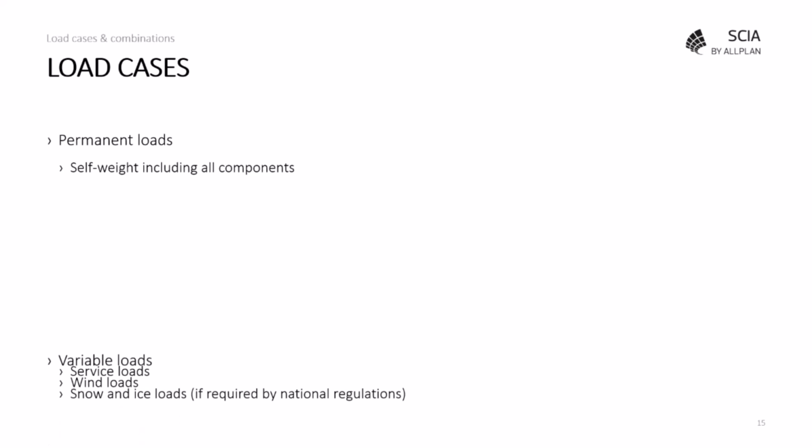So let's start with the load cases. We can define permanent loads, so that will be our self-weight. That can include other components. Maybe you want to add the load of the toe boards, but you didn't model them, so then they can be added as a permanent load.